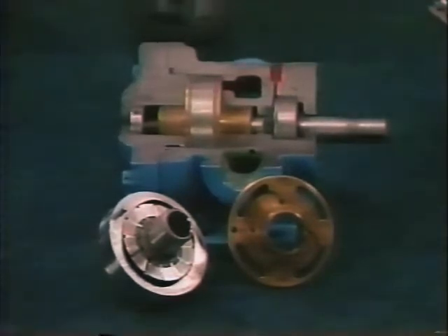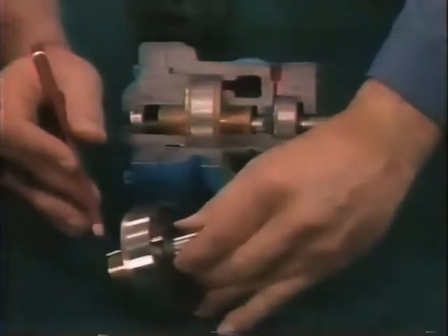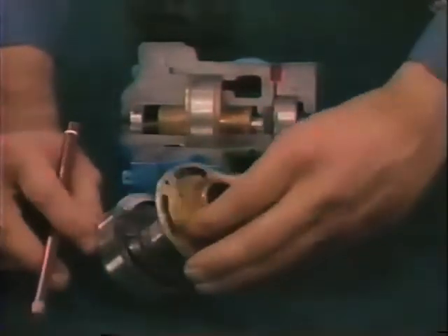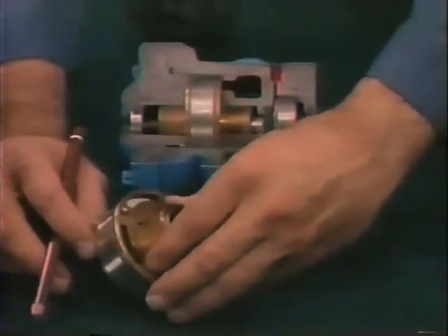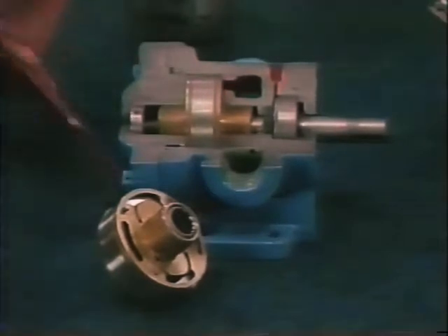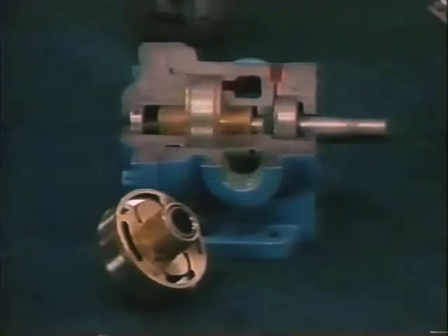A 2-diameter pin keys the cartridge assembly together and fits into one of two holes in the pump body, which are located 90 degrees apart. The hole that we select determines whether the pump is assembled for right or left-hand rotation. The pump cover serves as a clamp to hold the cartridge assembly together. Care must be exercised when tightening the cover bolts, as over-tightening may cause the pump to seize. Under-tightening will result in loss of efficiency.